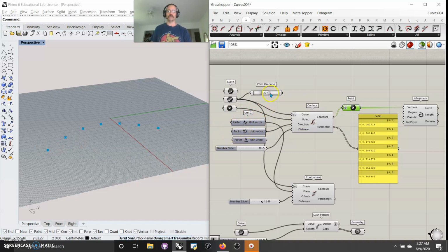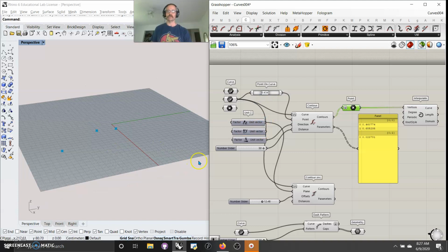The other thing you can do, which is very interesting, is change your direction planes. If I put back this point tool here and play with that, and change it to the x-axis, x direction, I get a totally different, mirrored, reflective imagery between those points. My size is so far split between here; I'm going to make it smaller so you can see some additional points. But look at how that Points on Curve is having an effect on where on that reparametrized curve I'm splitting it, and how I'm looking at it from different direction planes. So go to the z-plane and it changes it once again.